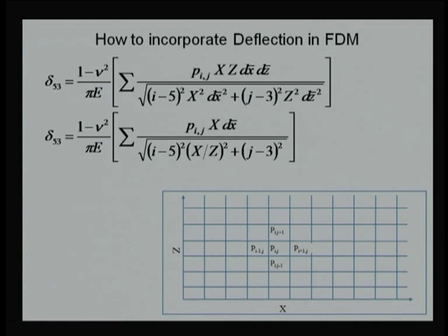In hydrodynamic lubrication, we took dx bar equal to dz bar. If those are not taken equal, then we cannot take this as common. We say that in this case we are taking both dx bar and dz bar out, assuming dx bar is equal to dz bar. Otherwise, we will not be able to take out, and as we have already done in the hydrodynamic lubrication mechanism, when we were solving the non-dimensional form of the Reynolds equation, we already took those assumptions. We are just repeating here.